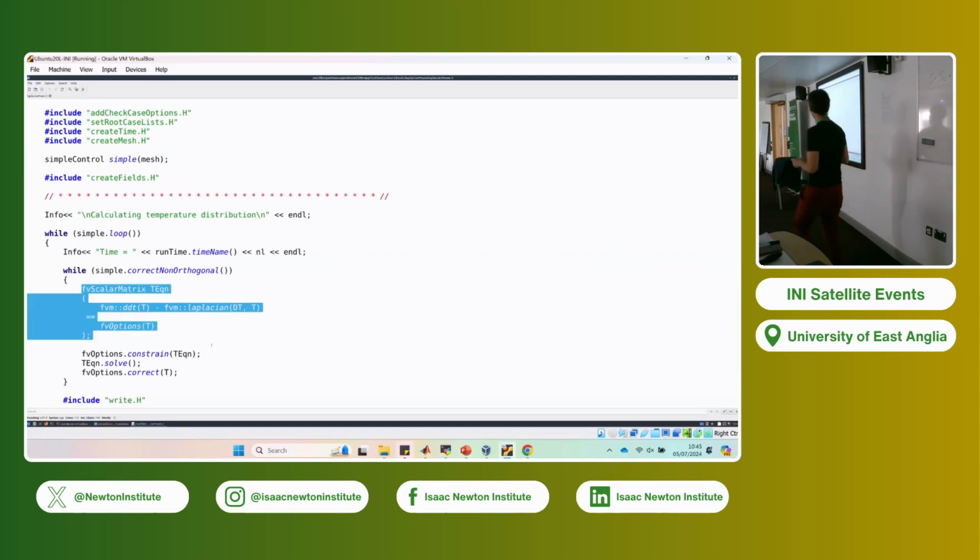You see, once you type ddt of temperature, you don't need to say in the solver which temporal discretization scheme to use. You can do that when you set up a case to use this solver, for example, to calculate the temperature on a square. It's when you set up your case file that you will say, well, use one of those discretization schemes I told you before, for example, Euler.